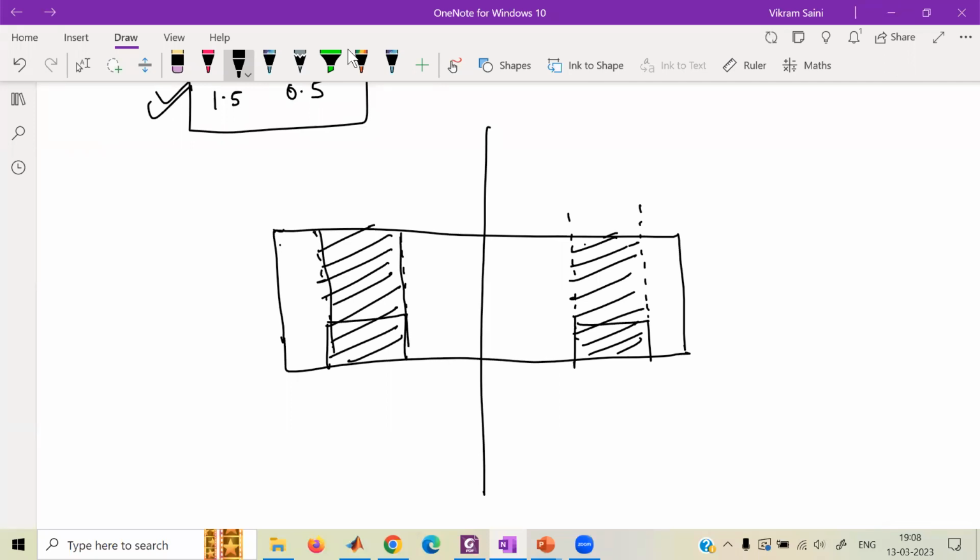So a certain change in lift is generated whenever you deploy this. On one part, delta L goes up, and on the other part, delta L goes minus from whatever lift you were generating earlier. Because of this change in lift on these two parts, you will have a certain moment.